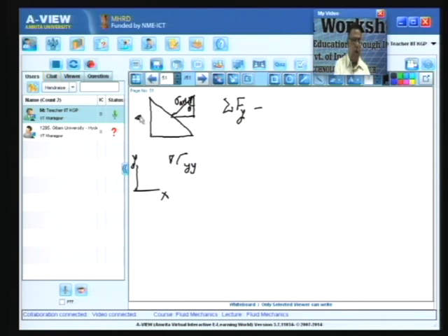This force will not play a role in the y component balance. So, this is going to be sigma_nn A_n, this is the force, sigma_nn is the intensity of the force multiplied by the area gives you the force in this direction. You want the vertical component. So, here that is going to be cos theta,